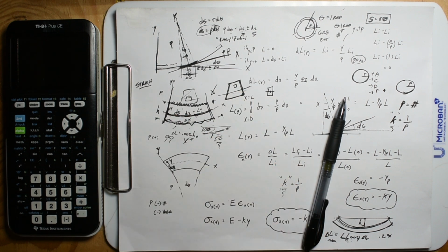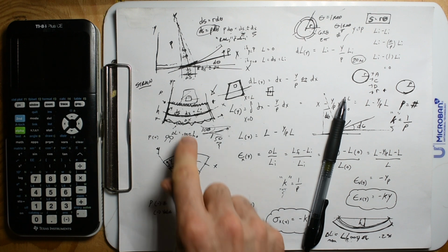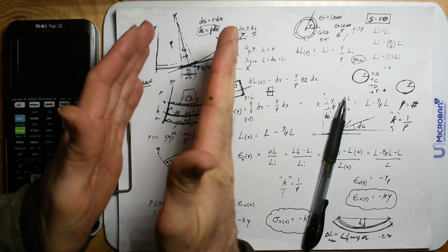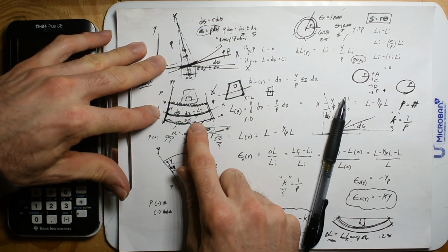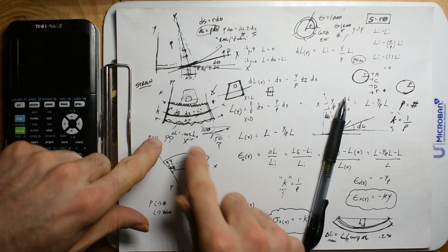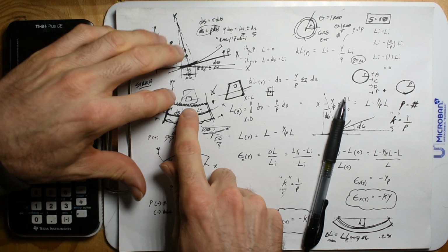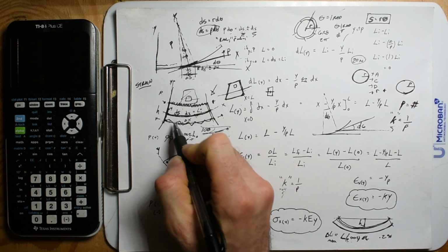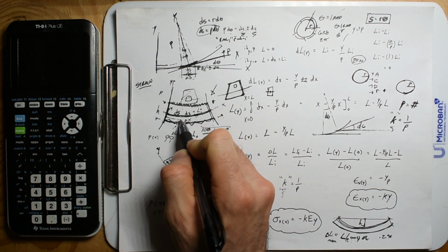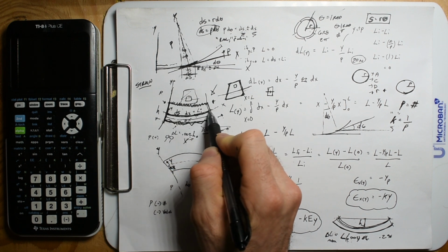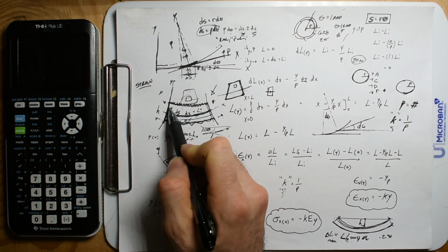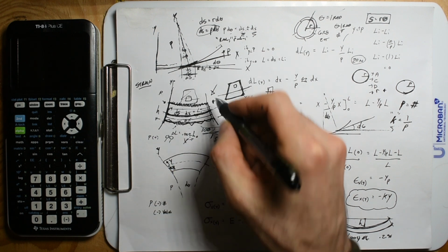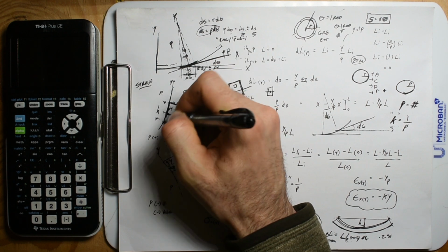We'll see that that's just based on geometry. What happens is that all the molecules stretch out or compress together evenly. So if I saw a big stretch out here, I would see half of that right there. I would see 0 at the neutral axis. So full, half, a quarter, three-quarters. It's linear.